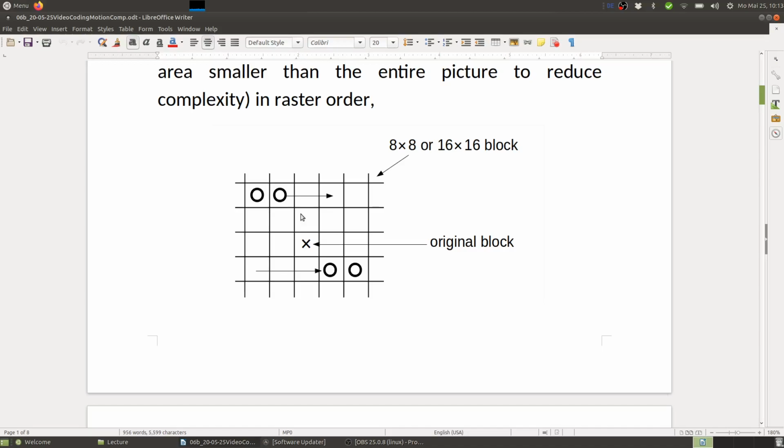If we now go to half pixel precision, then we have a factor of 2 in each dimension, which means a factor of 4, so 4000 positions. That's a lot of work. And for each of those positions, we have to compute the mean squared error, which again consists of 8 by 8 differences squared.